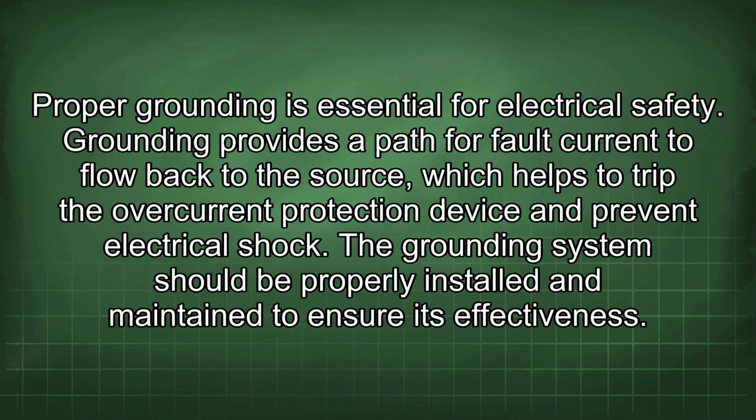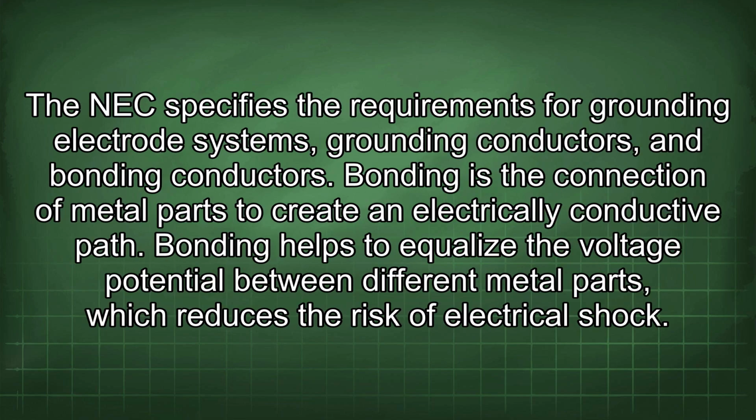Proper grounding is essential for electrical safety. Grounding provides a path for fault current to flow back to the source, which helps to trip the overcurrent protection device and prevent electrical shock. The grounding system should be properly installed and maintained to ensure its effectiveness. The NEC specifies the requirements for grounding electrode systems, grounding conductors, and bonding conductors.